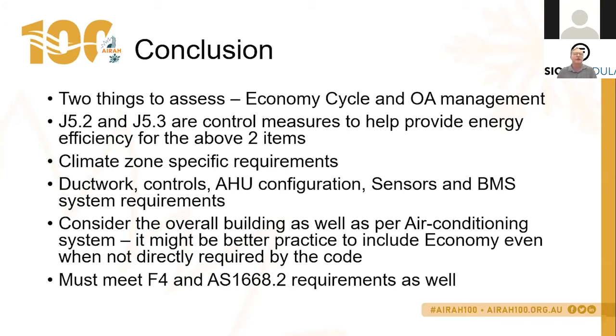So the practice of splitting into two systems in a foyer, if you split it into two systems and you design those two systems quite well, you could actually control the two systems so that at low load only one system runs. So then you'll get the energy saving required anyway. It may not quite give you as good an energy saving as being able to use economy cycle, but it'll still give you an energy saving. Up to you how you go about designing those systems.